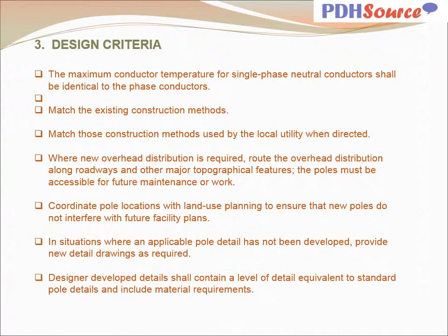Where new overhead distribution is required, route the overhead distribution along roadways and other major topographical features. The poles must be accessible for future maintenance or work. Coordinate pole locations with land use planning to ensure that new poles do not interfere with future facility plans.